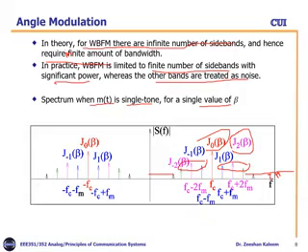So you can notice that these values are different, right? J1 is different, J2 is different. Similarly, their negative parts, J minus 1, J minus 2. And this is the overall negative image of this complete spectrum: minus FC, minus FC plus FM, minus FC minus FM, right? So this is the spectrum of a single tone wideband FM.